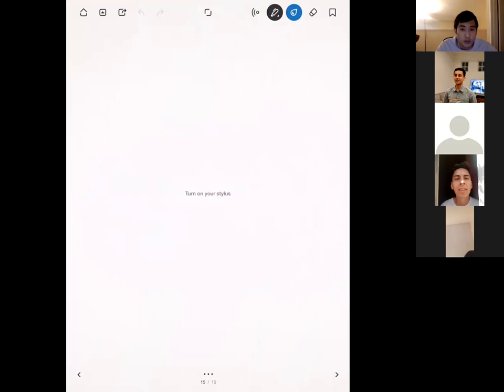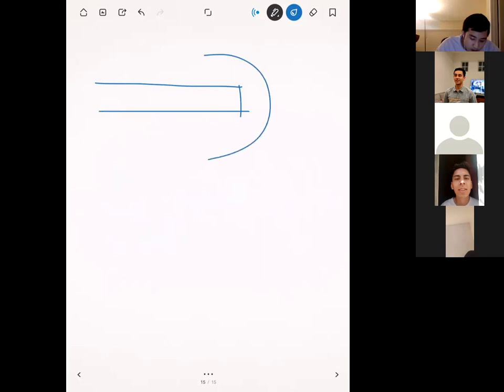No, the moments would have to be explicit. Unfortunately, I didn't give you any examples of this, but usually when I want you to apply a moment, it would look something like this in the diagram. You would have your beam, and I would put a circly thing like that. So if there is no applied moment, we don't assume there's one induced from a force? Correct. Any induced moments will already be taken care of in the system. When I have an applied moment, that's literally someone grabbing it and twisting it like that. So it's not the same thing as a force going down.